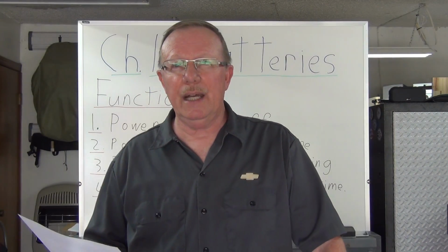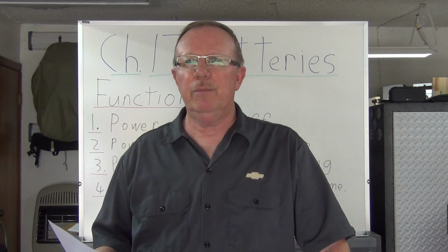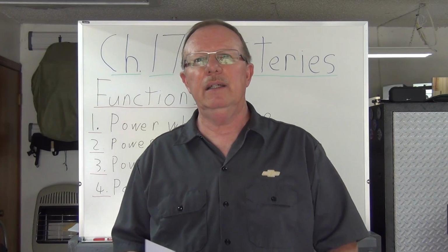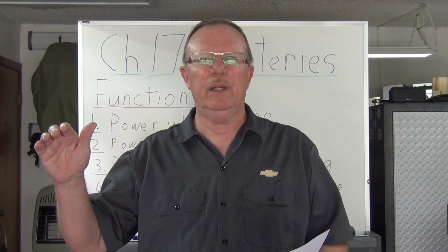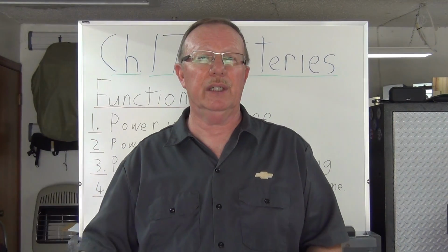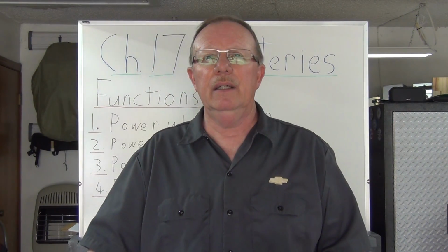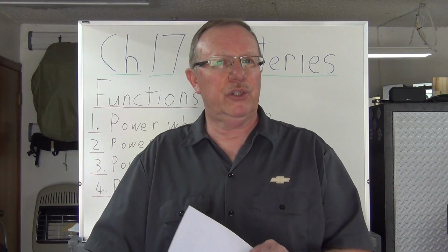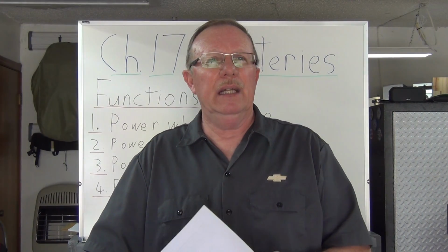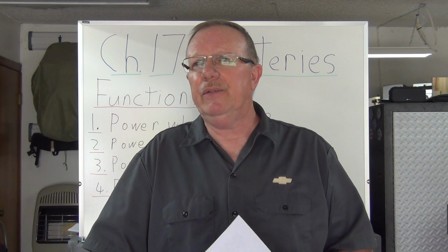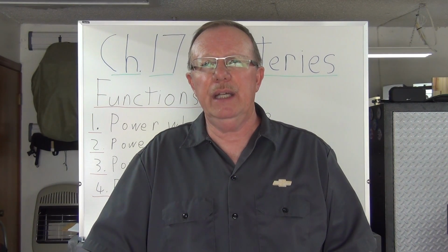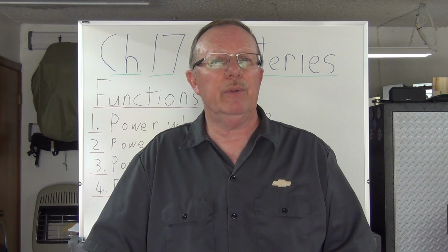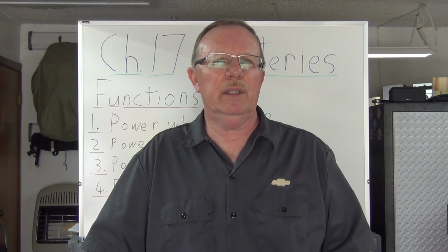Automotive batteries are not designed to be deep cycle batteries. Automotive batteries are designed to be maintained all the time, at the top at 12.6 volts. They're designed to be not discharged all the way down and back up. Now they can do that a couple of times, and if something happens to the battery, something's left on and the battery goes dead, it can be charged back up and it can recover from that. But that's like a one-time thing, or something happens very occasionally.